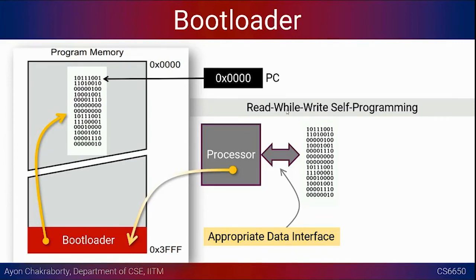Okay, but still it is inherently complex because they have to start different mechanisms inside the microcontroller, right? This is the bare hardware that somebody has given you, and the bootloader sort of brings life to it. All the different hardware has to be initialized with proper values, and the different memory locations have to be pointed to, to make it function. You have this BIOS in your desktop, the way it basically chooses an operating system and loads that operating system in memory.